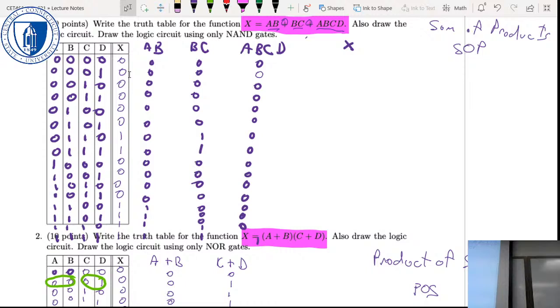So to get an AND, 2-input AND gate out of a NAND gate, we have a NAND gate, and then the output of that NAND gate goes into 2 inputs of another NAND gate, which effectively negates the output. Right, so you end up with an overall AND.